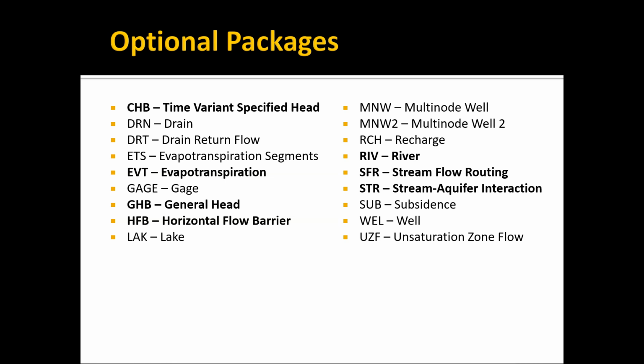There's the UZF, unsaturated zone flow package. That's for simulating flow in the vadose zone, which you don't normally need to worry about, but you can. The drain return flow allows you to take water that goes out to a drain and re-inject it somewhere else in the model.